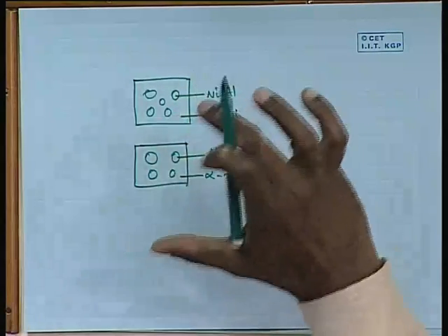So this is the one which tells you that you can have very good strengthening. You have ordered FCC particles in an aluminum matrix, and you will also have sufficient ductility, because alpha aluminum is FCC, so good ductility, and the ordered particle is also the cubic ordered, not really tetragonal or orthorhombic. Cubic phases always have a higher ductility because of what? Where from does ductility come? Close packed nature of the planes and directions.